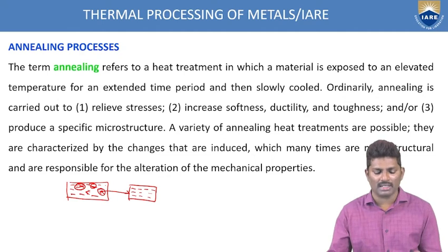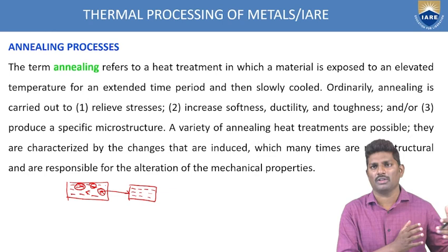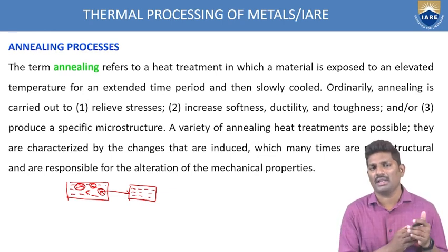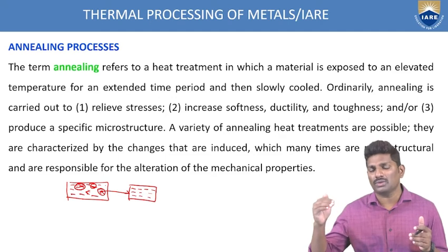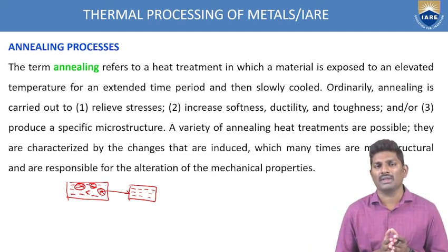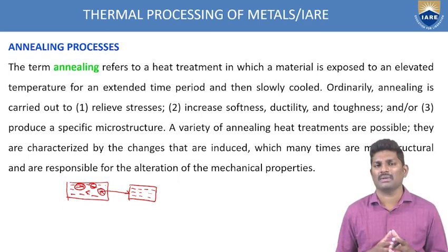So the term annealing refers to the heat treatment in which the material is exposed to elevated high temperatures for an extended time period. You have to heat the system for some time, then only you can get the even structure. And after heating, you have to let it go through a slow cooling process. You should not do immediate cooling. Again, if you do immediate cooling, what happens? The formation of cracks, everything will happen.